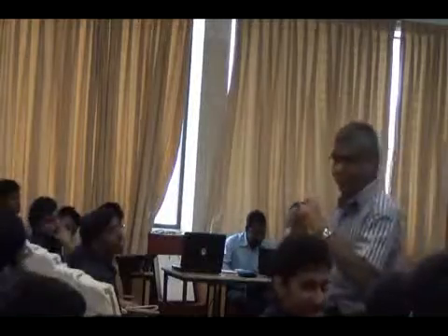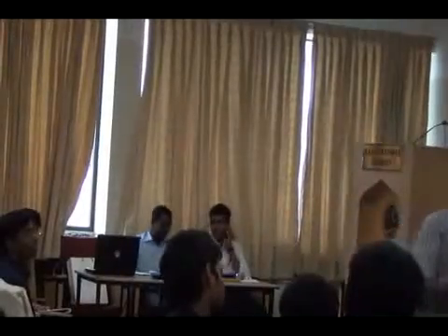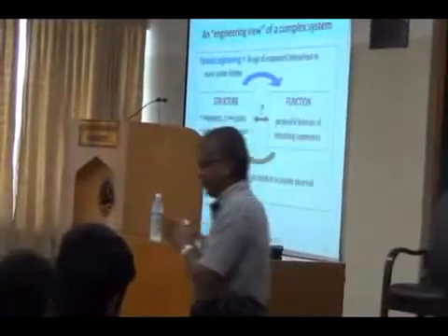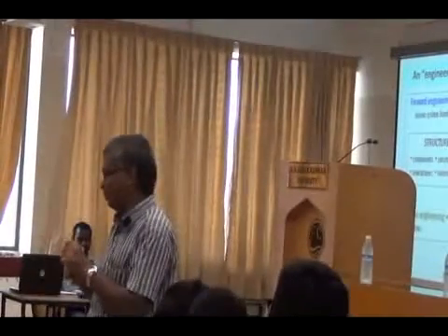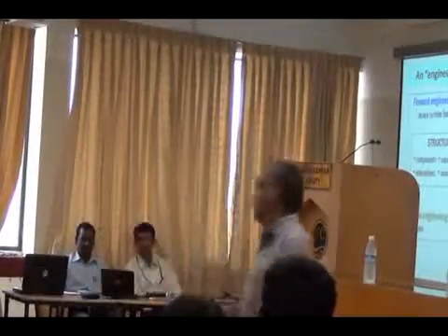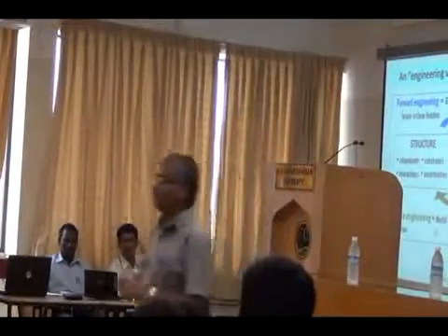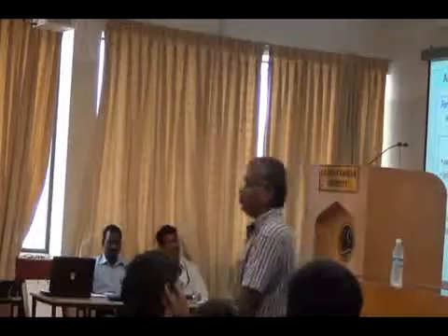It means end of the story because you take the gearbox, the gear tooth alone, two gears meshing with each other. Without a gearbox, power is not going to be transmitted. These are made of two different materials, or the same material. Same material, same hardness. Material properties, hardness. Then the wear rate will be some number. The wear of the gear tooth will be some number. Suppose these two gears are of different materials, what is likely to happen? One material has a higher hardness, the other a lower hardness. The lower hardness material will wear fast.